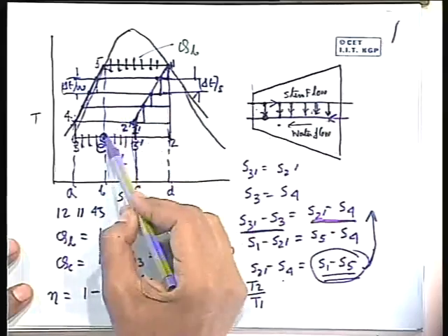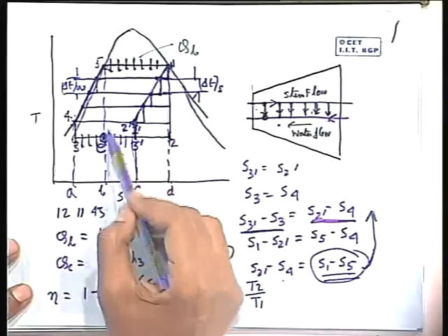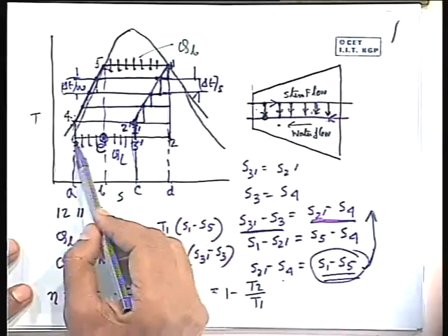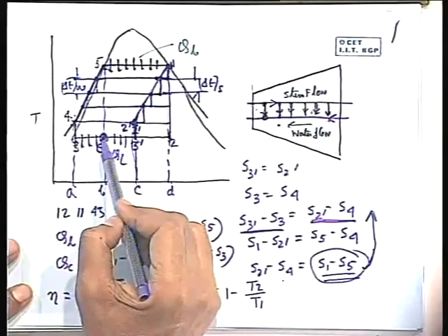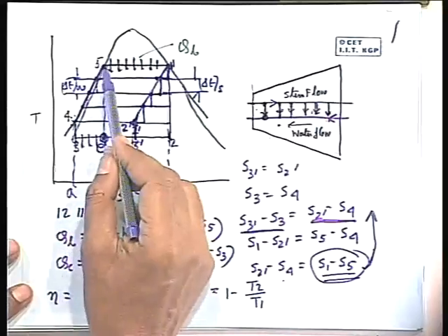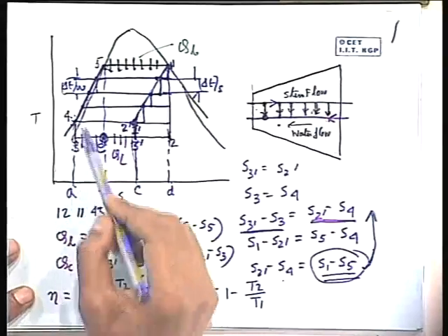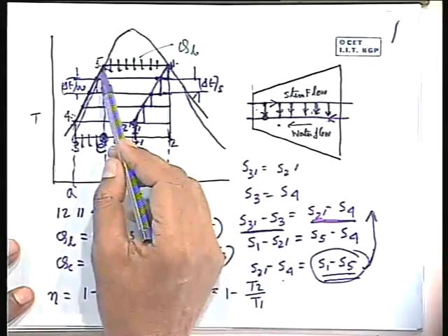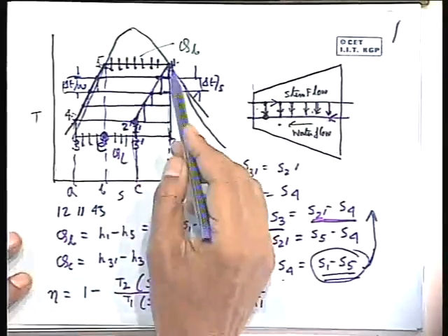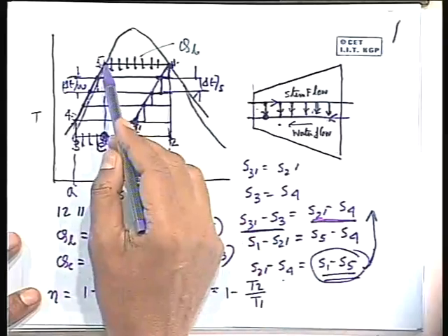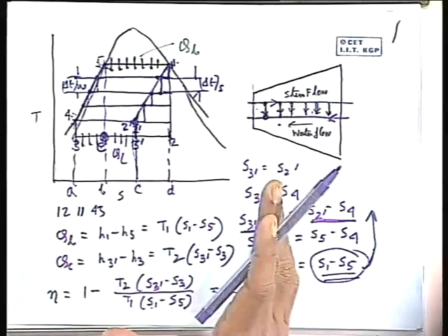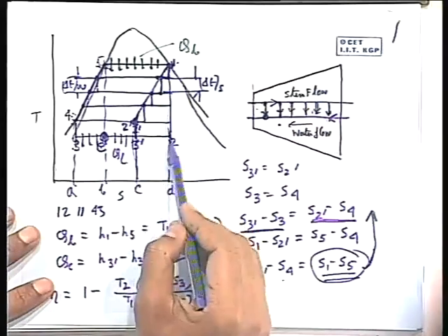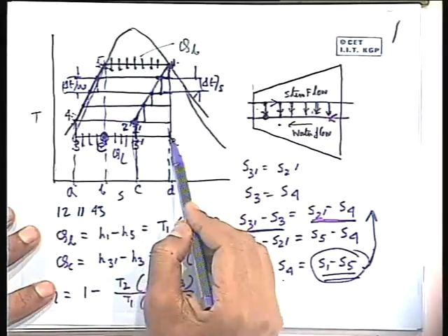That means the rectangle, which is the Carnot cycle, is deducted by this area 1, 2, 3 dash, 2 dash, and on the other side, on this half of this rectangle, I am adding this 5, E, 3, 4. That means this area 3, 4, 5, 1, 2 dash, 3 dash is identical to 1, 2, E, 5. Understand? It is equivalent to that. So this rhombus type cycle diagram is equivalent to the rectangular cycle diagram corresponding to the Carnot cycle.